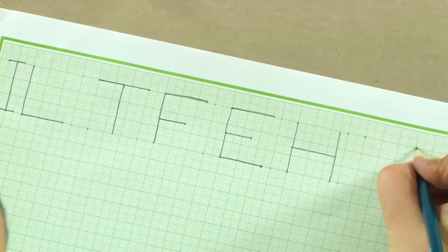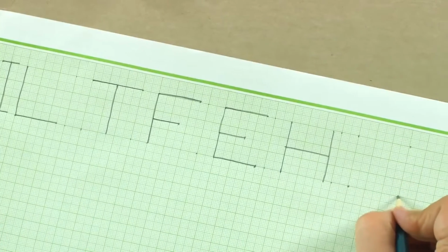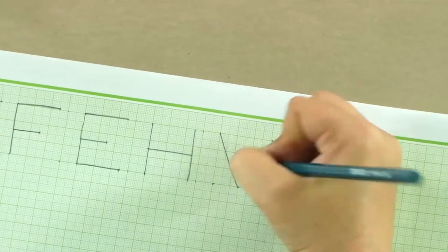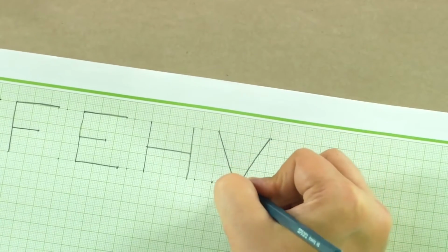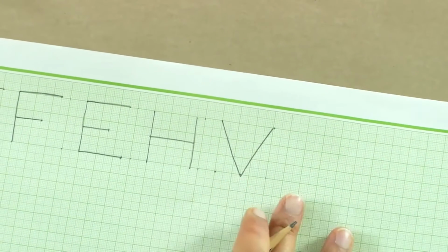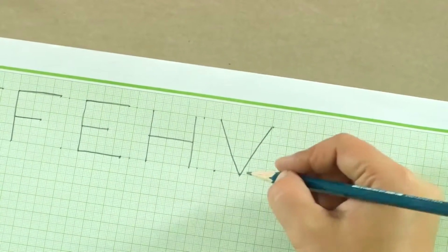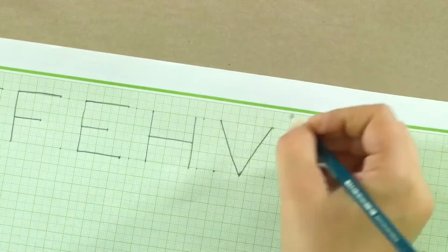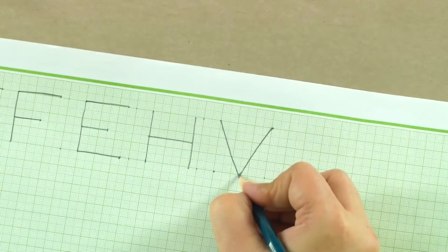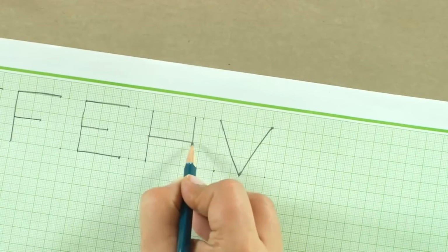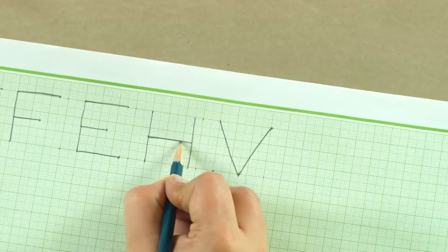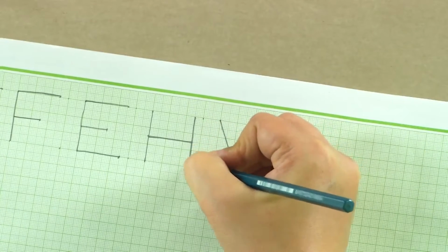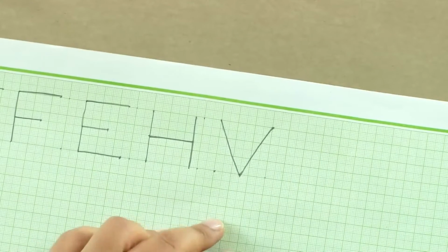V is a 6 by 6 alphabet. Remember the strokes as I make them. In almost all cases, you never draw a line from bottom towards the top. You will always draw a line from the top to the bottom, which is how you normally write as well, and from left to right. So, if you have to make a horizontal line, it has to be left to right, and top to bottom is how a curve, any line while lettering will be drawn.